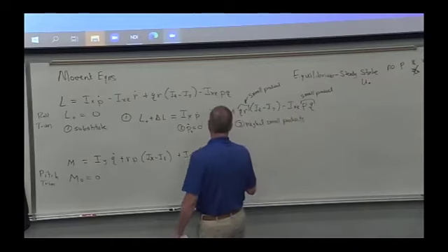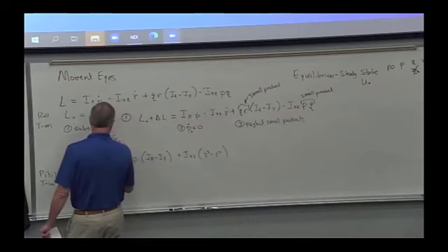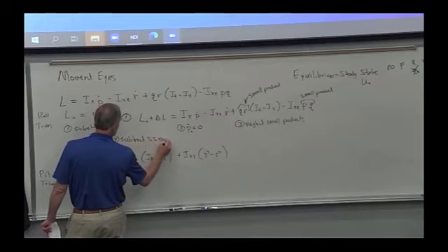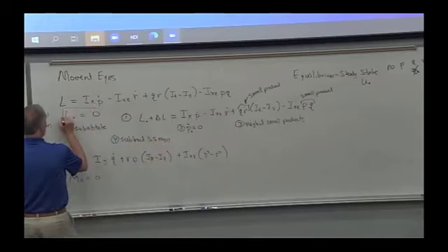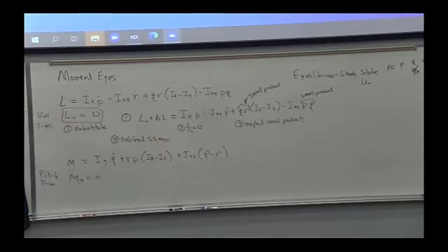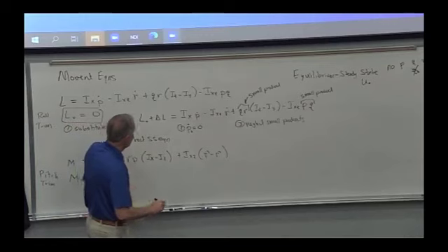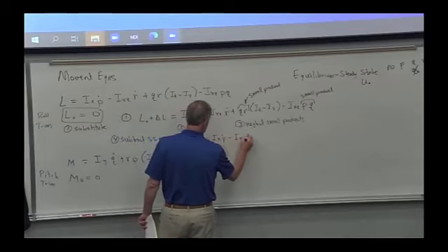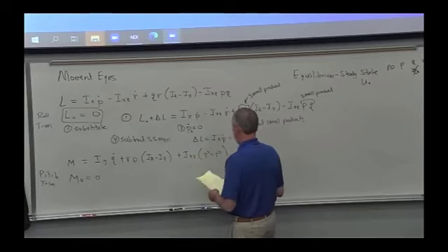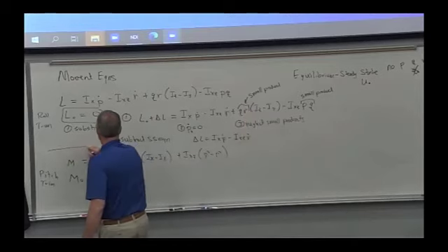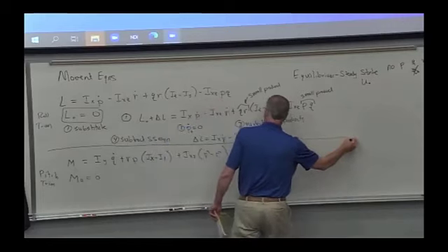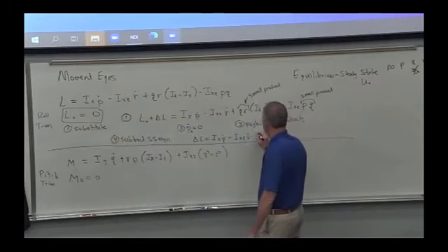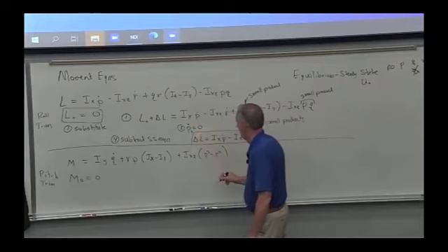So that's step three, and then step four is to subtract the steady state equation. And this is super easy because the steady state equations are just this. So that means the only steady state part you see is the L0. So then you get that's gone, that's gone. So I think that's it. Let me draw a line here because I kind of crammed the stuff together. So this is our small perturbation rolling moment equation.